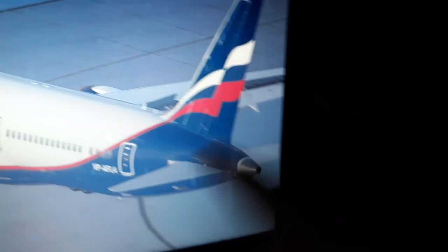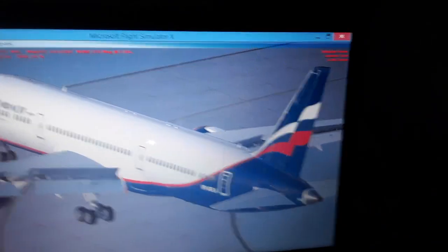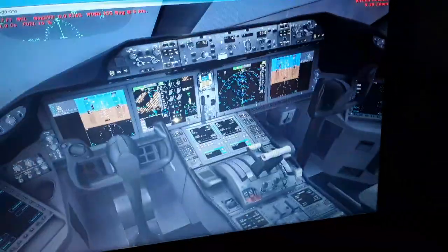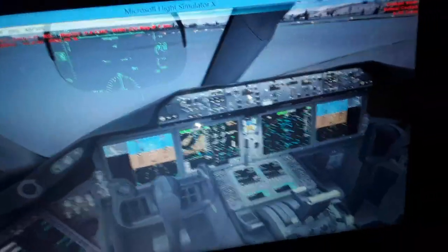We have the auto trim, and the normal horizontal stabilizer trim here for the elevator as we climb and as we descend the aircraft. Climb, descend, also horizontal stabilizer trim, automatic and manual. Automatic is by the aircraft's own flight control computers. We have, like in the Airbus, the normal, alternate, and direct modes.